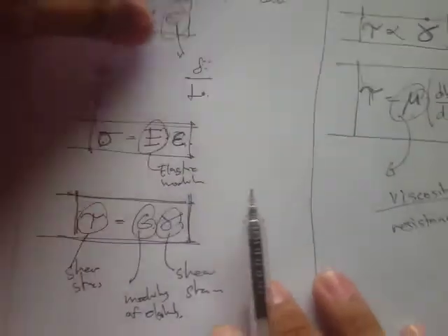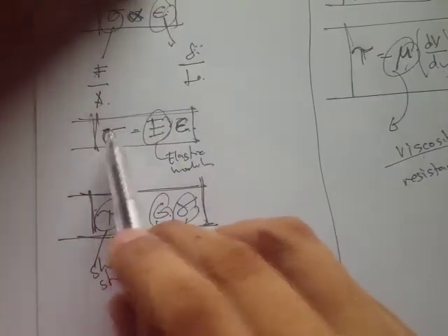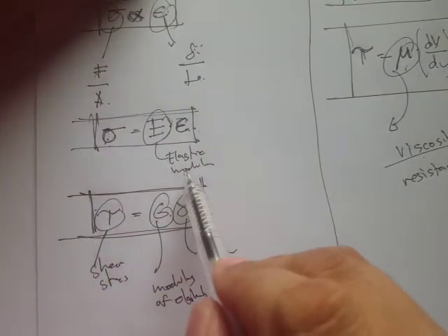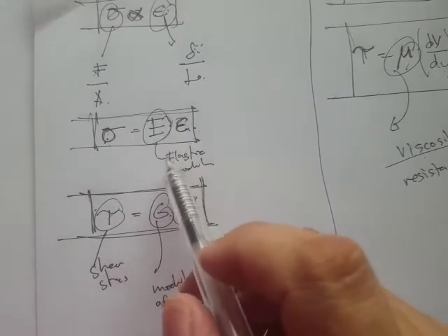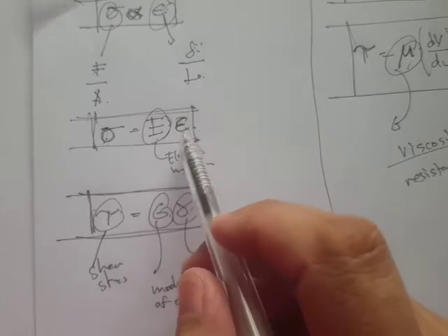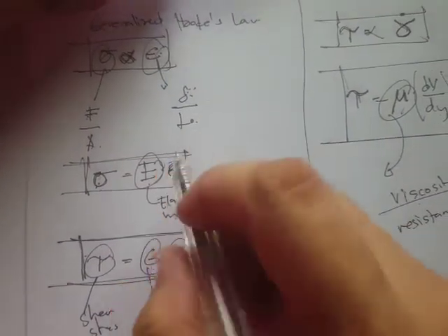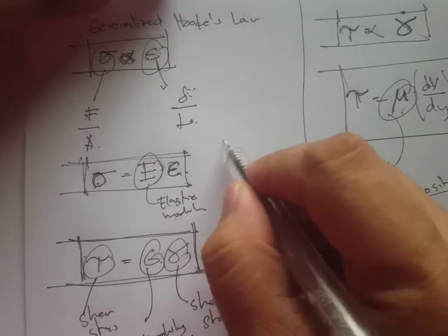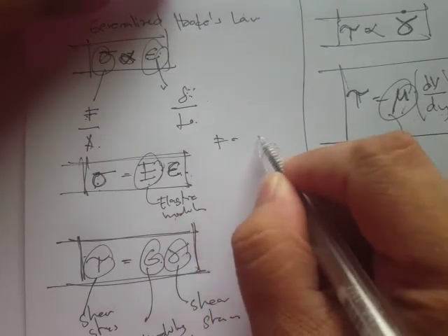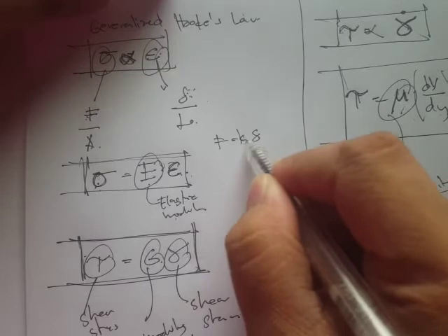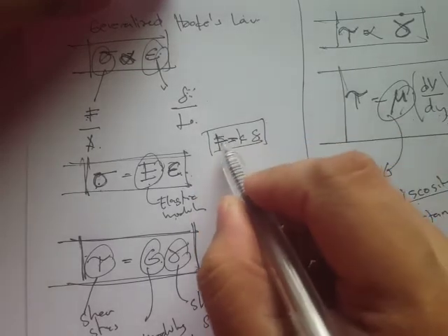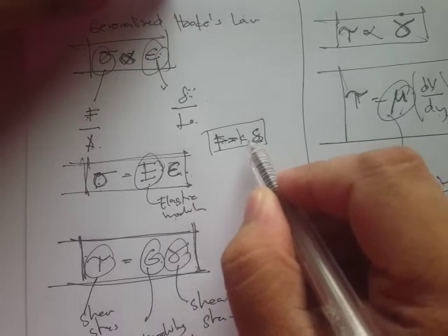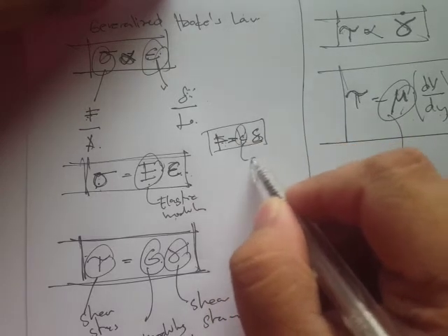Okay, the same way with this. If you have a high elastic modulus, then it requires higher force in order to deform. Okay, so again, you might also encounter this: force is directly proportional to the deformation by this constant. Now, if it's just F and deformation, then this one is stiffness.